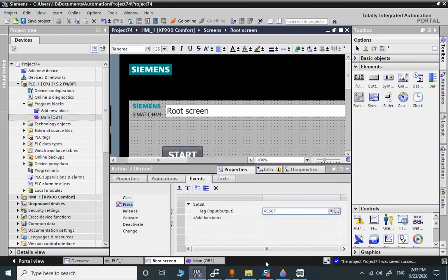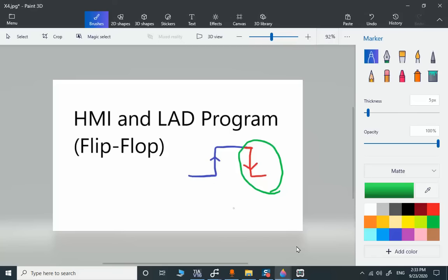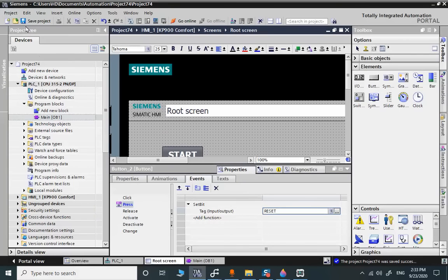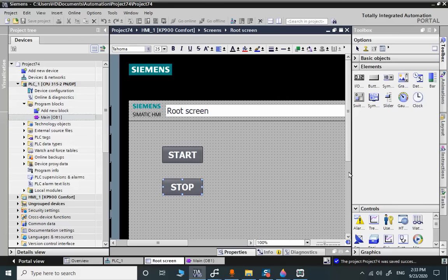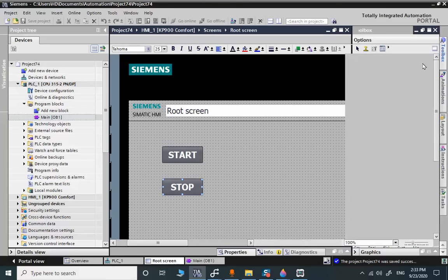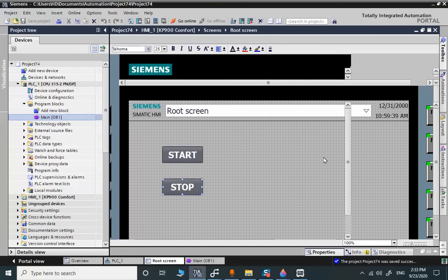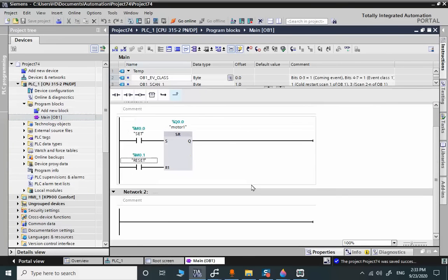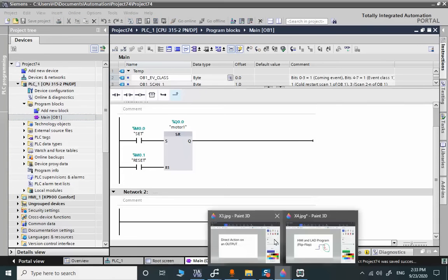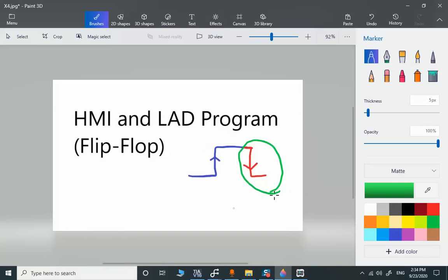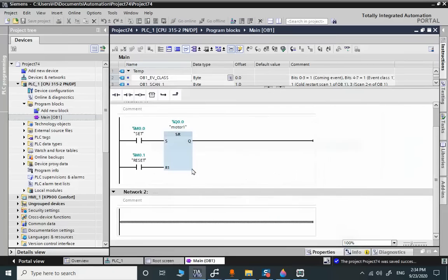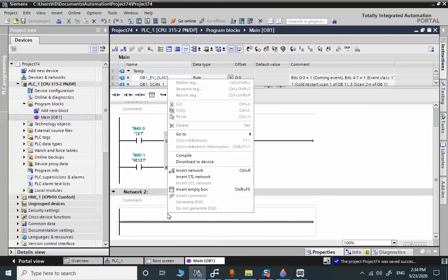So we use the HMI to set two signals, but in user program we don't need to keep them always true. It's a big trouble for us for rest of the program, and we need to reset these two signals. This red section will be done in the user program.